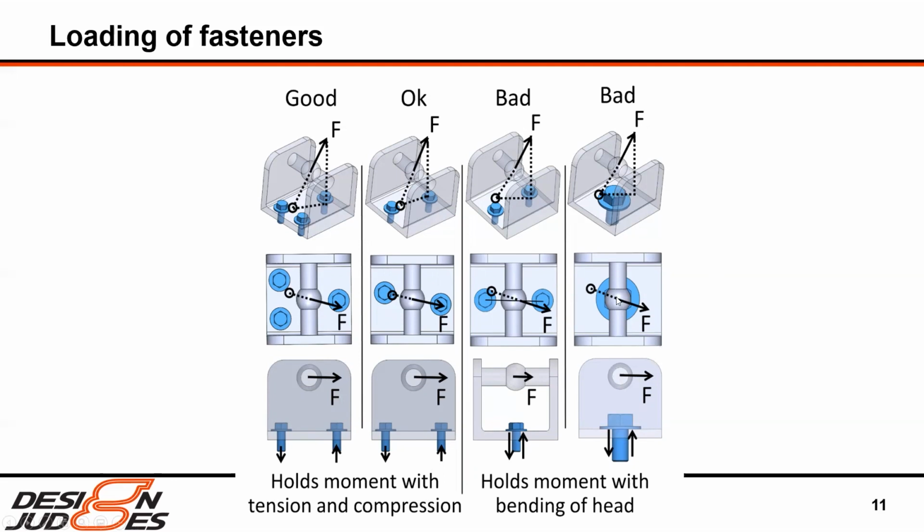And so in the top view, it's going along here. And so you think, oh, I'll just put one big bolt, I can make it strong enough. Well, the issue here is that in the side plane, the horizontal component, obviously it's acting up in this plane too, but just for simplicity, you're going to be reacting this force over this length with bending in the head. And so you're really going to be prying this head off and breaking this head prematurely.